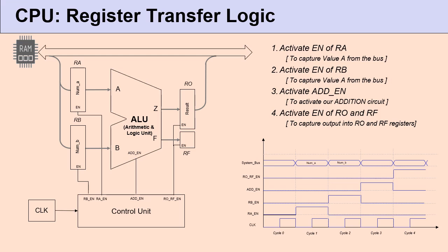For example, if the CPU design is such that the RTL has many steps for each operation, even at the same clock speed, that will take more time to complete each of these operations because of the higher number of steps involved. A CPU which has few steps in the RTL logic for each instruction will run much faster even at a slower clock rate because of the few operations that need to be carried out.